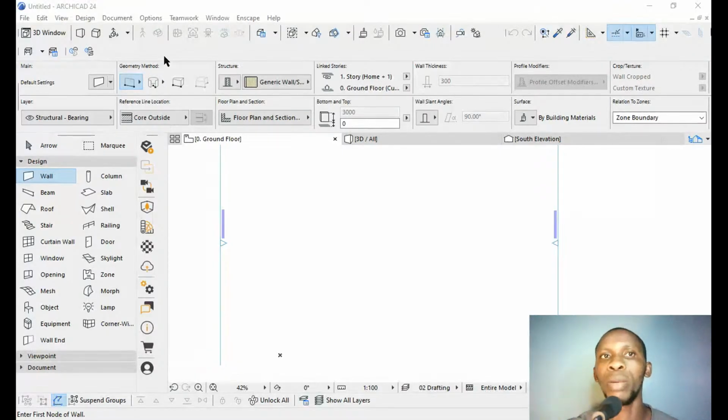That one is very, very important because here you can choose the wall height, the width of the block wall, and then you can choose how you edit the height of the wall, or whatever kind of wall you want to make it. So now the first thing is top link, right? You click on top link and then you click on not linked. I usually click on not linked. Why? So that I can actually edit. Let me show you what happens.